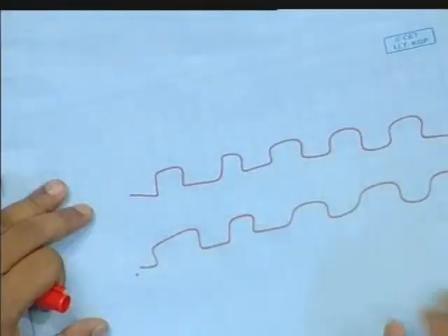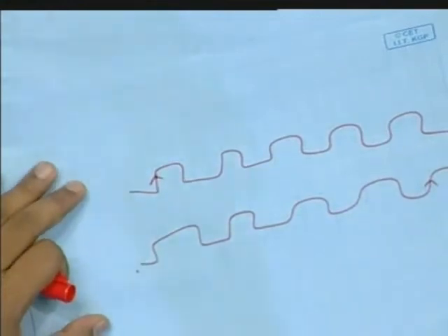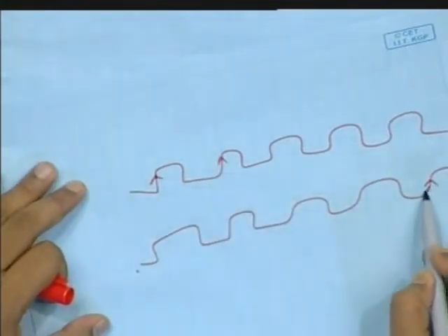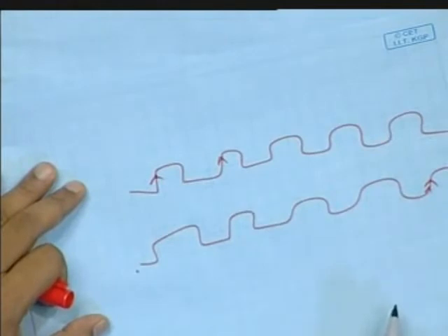See, multi-cycle path means what? Your clock is moving like this, right? So this is a capture clock. It may not always be at the same frequency. Say you are doing the setup analysis between this and this. It may happen that you are doing the hold analysis with respect to this edge. It may happen.